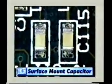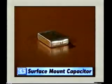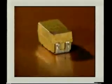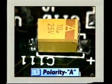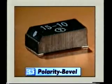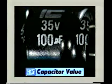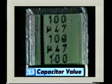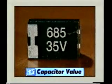Surface mount capacitors are often chip style. They have metallized terminations on each end of a ceramic body, usually wrapping around the end on all 5 sides. Polarized surface mount capacitors will have the direction of polarity or installation marked by a line or letter A, or by a beveled edge on the positive end. Writing on both through-hole and surface mount capacitors will indicate the value in picofarads, nanofarads, or microfarads.